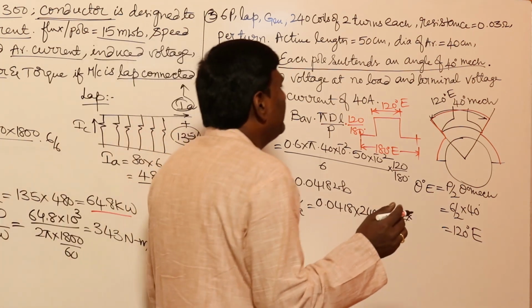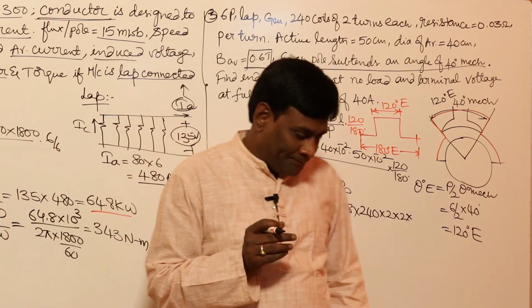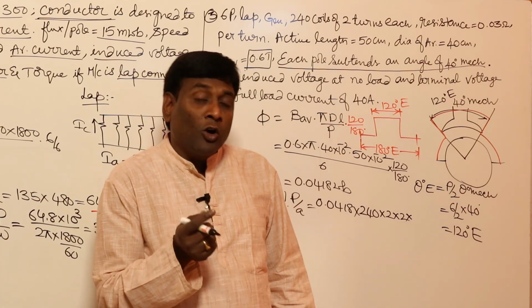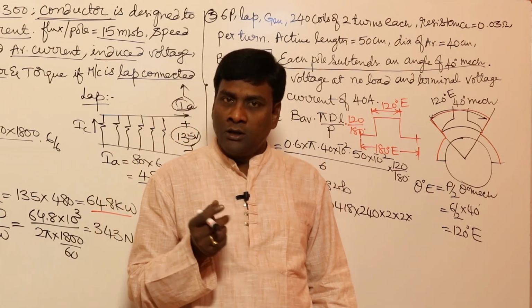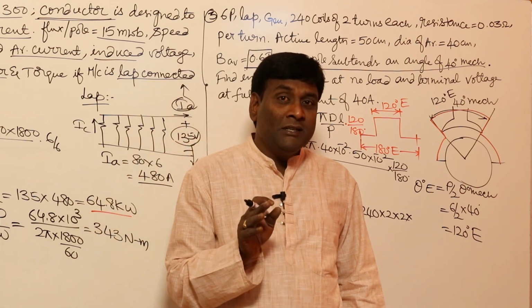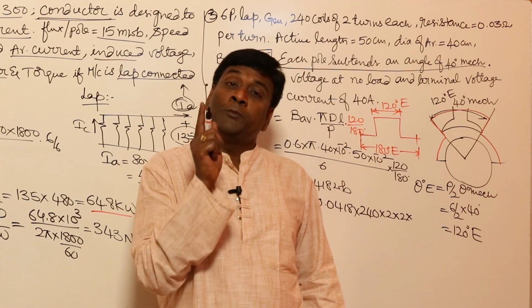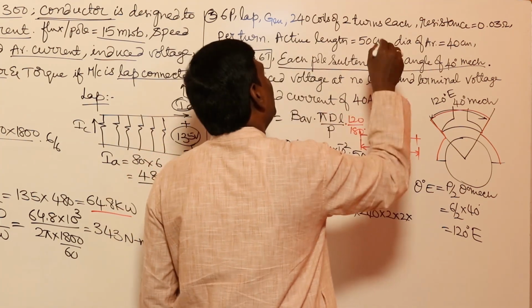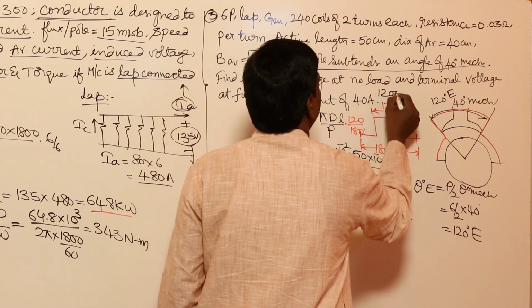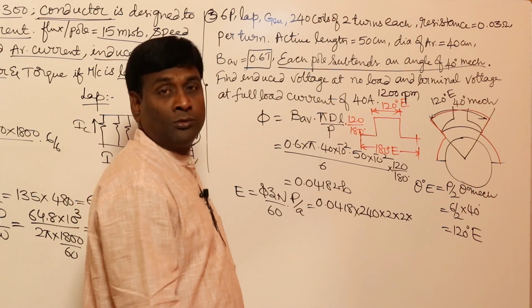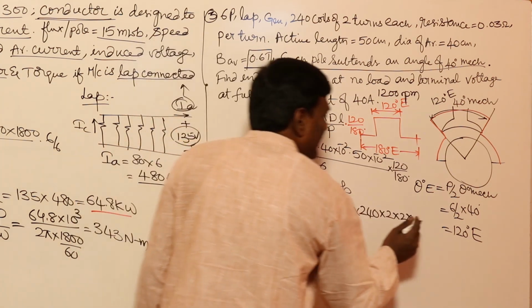Okay. Anyway, because of this, let me tell you one small thing. For example, in a synchronous machine, if poles and frequency are given, automatically we can find speed of armature, or speed of rotor we can say. But here in DC machine, it can rotate at any speed, so speed should be given by the problem only. Actually in the problem they have given 1200 rpm as the speed. I'm sorry, I forgot to enter it. So 1200 rpm.